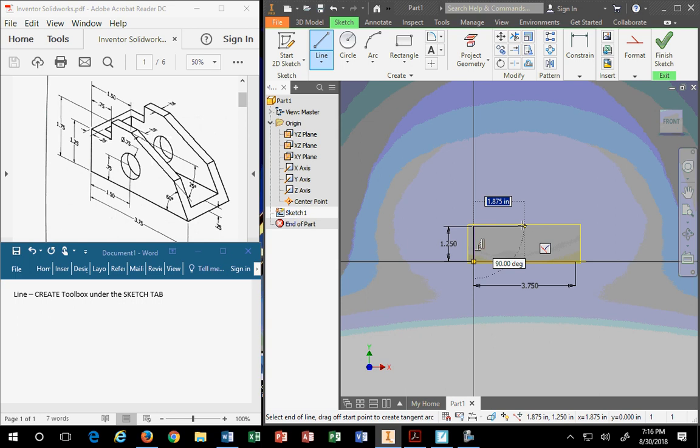Do you see that one? That upside down T means perpendicular. It's exactly the same one you'd see in math class, in geometry class, in metrology, GD&T symbols. Got it? So it's perpendicular. The other one is the vertical reference, and then what you're seeing is that other line is just saying, hey, I'm going somewhere. Don't know where, but I'm going out there.